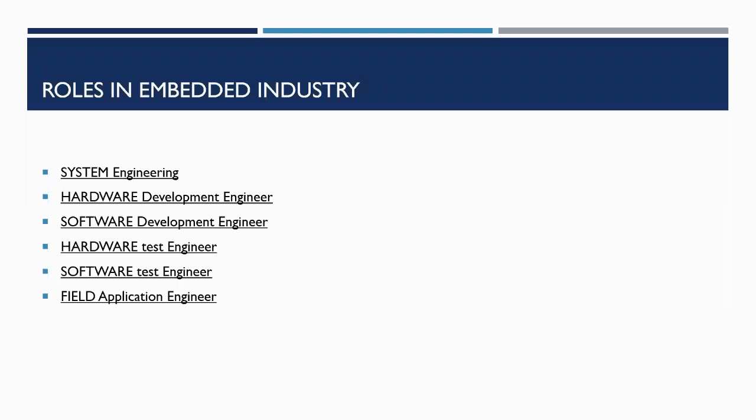These components, along with the circuit diagram, have to be made, and then they have to implement the same circuit diagram on a PCB, and once they give the 230 volt input supply, the expected output is 12 volt. This needs to be checked. For this, they should carry a good multimeter, and an oscilloscope is also good to have.